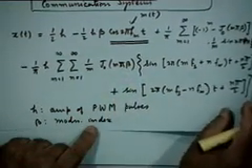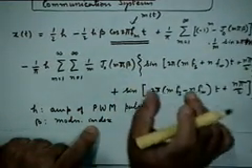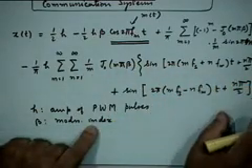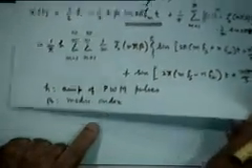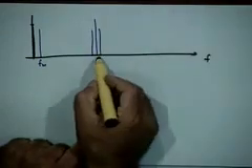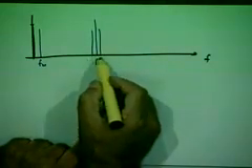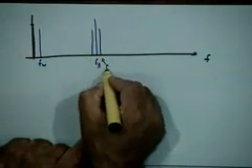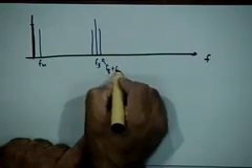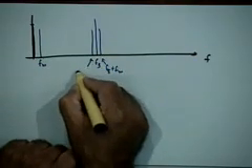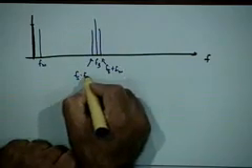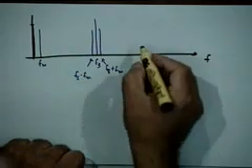So when beta is very, very small, that is, you are using only a fraction of the maximum possible width that you can have, then around fs also you have only two components, namely fs plus fm and fs minus fm. It becomes like narrowband FM.